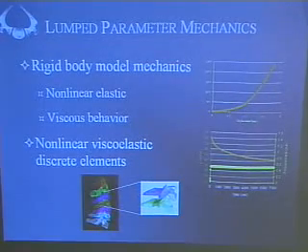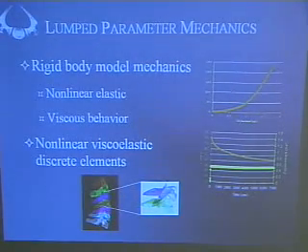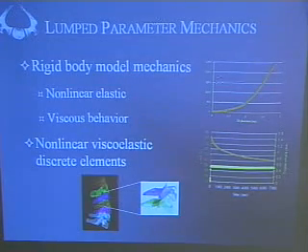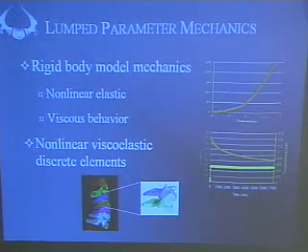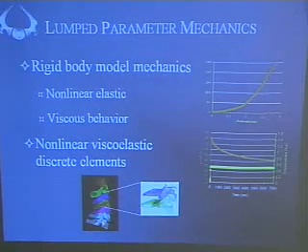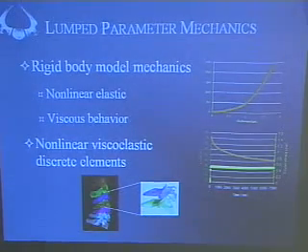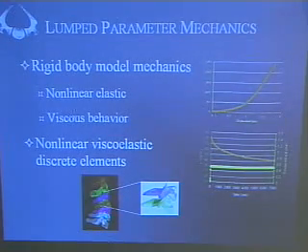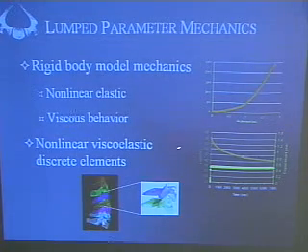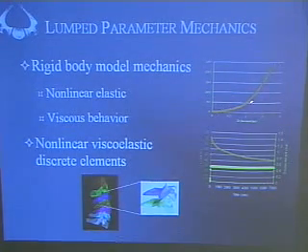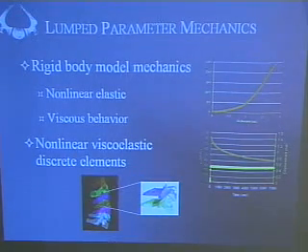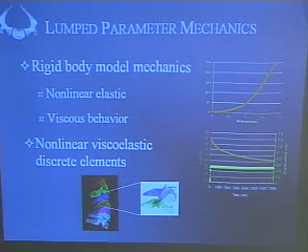To model those intervertebral mechanics, we chose lumped parameter components. And we really needed to figure out how we are going to model those. There's a bunch of different ways you can model them. It's just as linear elements, elastic, no rate dependence. But we decided to turn back to our experimental data. And what we saw is on the load displacement curve, this is load here, displacement here, as you increase in displacement, you see a nonlinear, and it almost appears exponential, elastic response of these tissues. So that led us down the road of selecting a nonlinear elastic model.